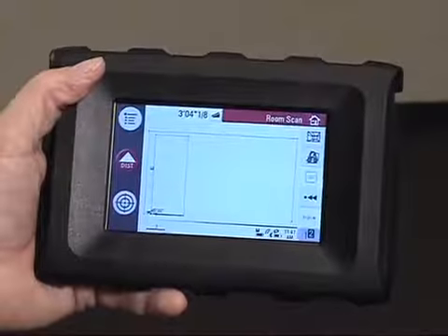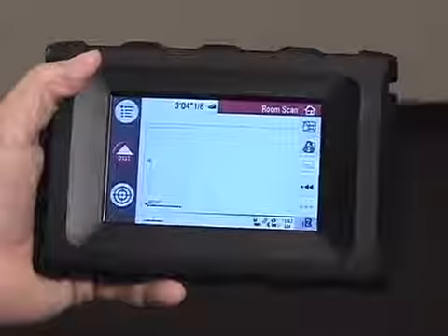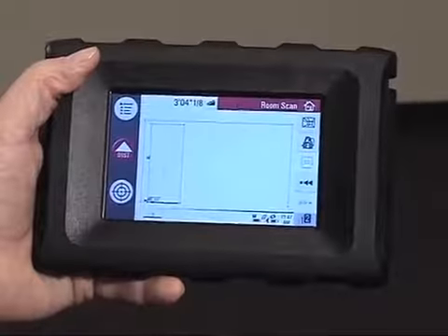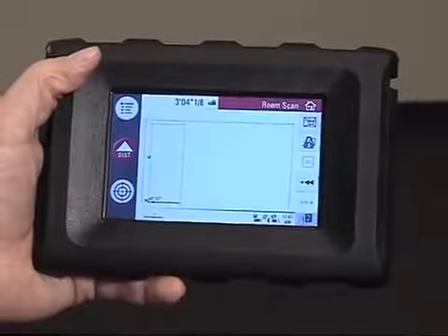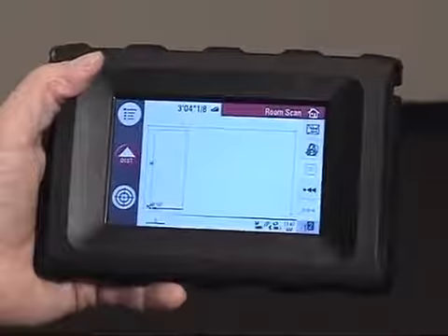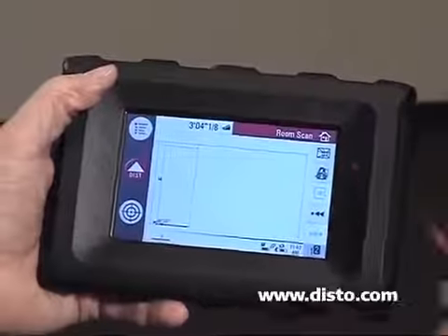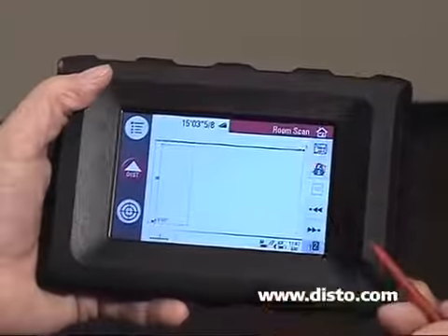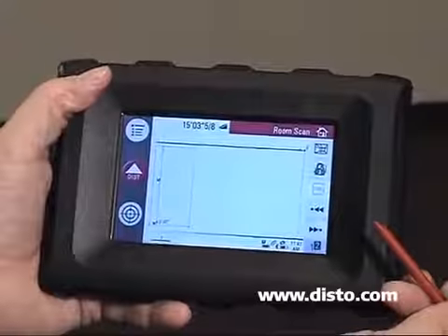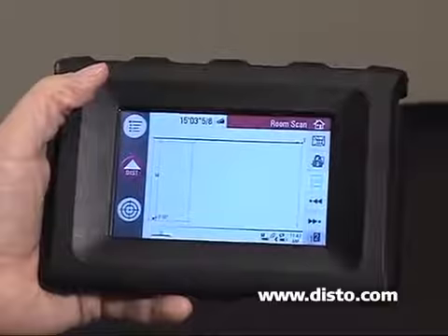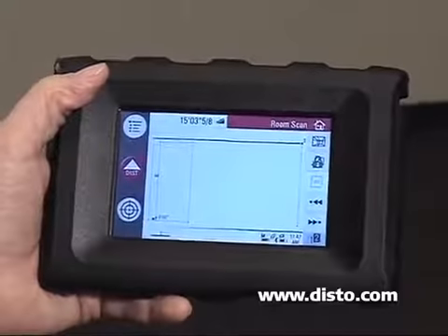Now that we've laid out our initial wall plane, there's typically more wall planes or more wall surfaces that are in the office. So let's go ahead and add a second wall plane to our drawing. The first thing that we're going to do is start by working from this top right corner, which is point 3, because the new line segment that I want to draw, I'm going to extend from point 3 way down the wall to the other end to our new point that we're going to establish.